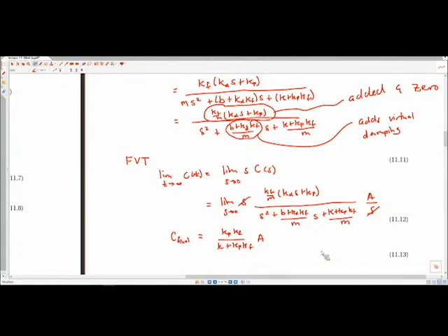Okay, so if you go back a few weeks, when we were talking about proportional control, you would have seen that C final was exactly the same as this. Okay, so this does not improve steady state response. So derivative control helps with the transient response, right? So if you have a system that used to oscillate wildly, you can add derivative control to it, and it's going to cause it to damp out those oscillations more quickly and less violently, but it's not going to actually help you when you get to steady state.